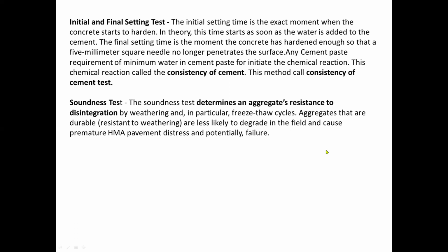Then we also have the soundness test. It determines an aggregate's resistance to disintegration by weathering, and in particular, freeze-thaw cycles. Aggregates that are durable, meaning resistant to weathering, are less likely to degrade in the field and cause premature HMA pavement distress and potentially failure.